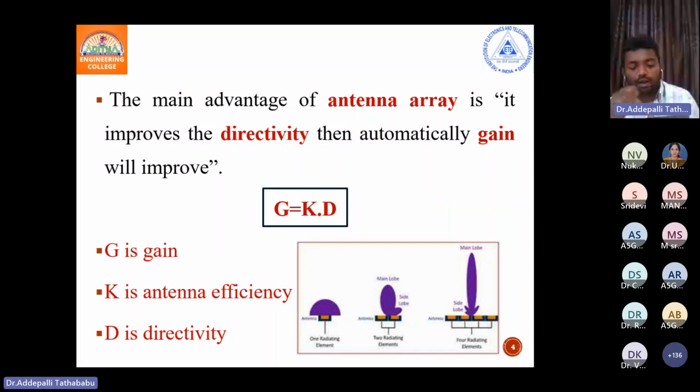If you consider the losses in the antenna, that is the conducting losses and dielectric losses, then 1 watt is applied, 50 is reflected, 950 is accepted. Suppose one more 50 milliwatts is lost in the antenna, and 900 milliwatts is sent into the free space. So the radiated power is 900. Previously 950, now it is 900. So 900 by 1 watt is the total efficiency.